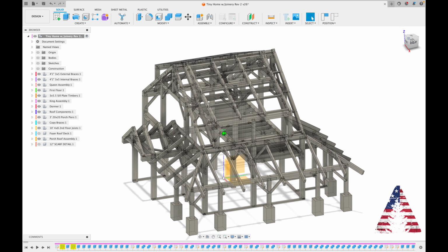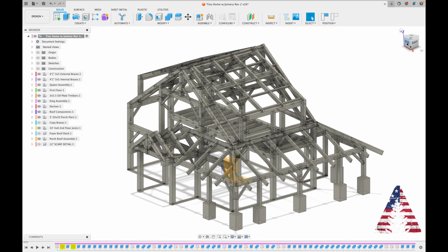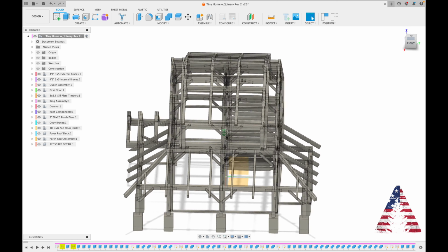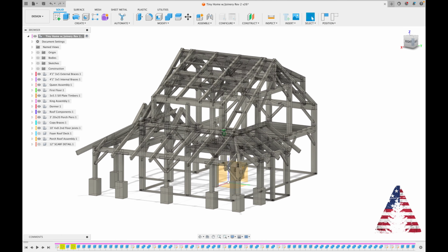I've got a nice roof profile here with a 9/12 or 9-pitch roof with a dormer. That's a 5-pitch roof here. Some dormer posts and beams, right? A second floor loft here with the floor joists, and in the back we've got space for a mechanical room.